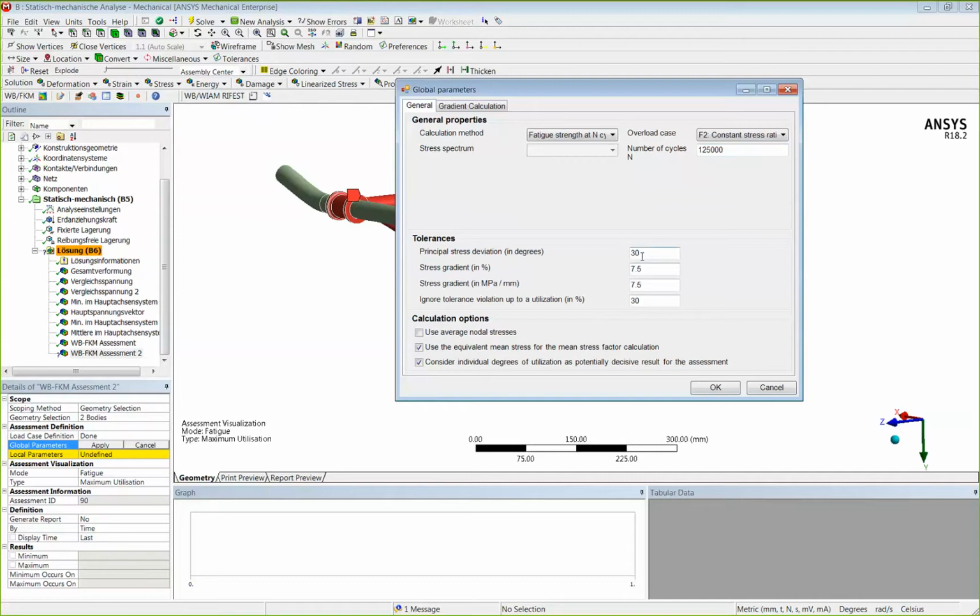That's usually the case when I have an unloaded surface or if I have a pressure on the surface. The only case where it's not like that is when I have friction on the surface. Then it wouldn't be totally true that one of the principal stresses is normal to the surface, but usually that's true. And for the guideline, it's always absolutely true.